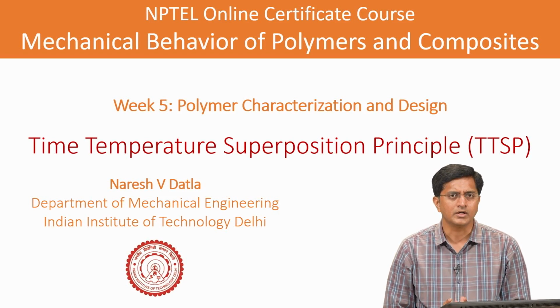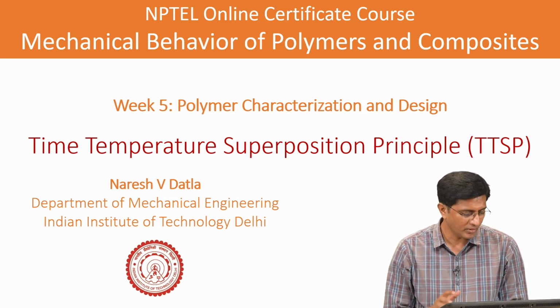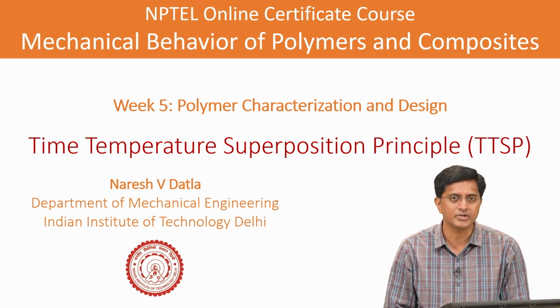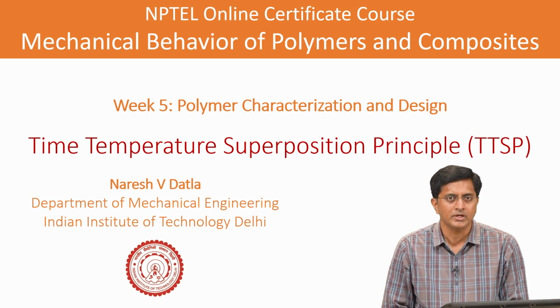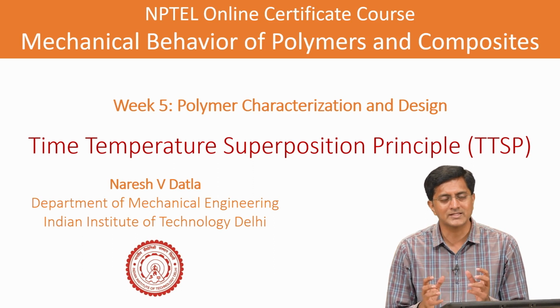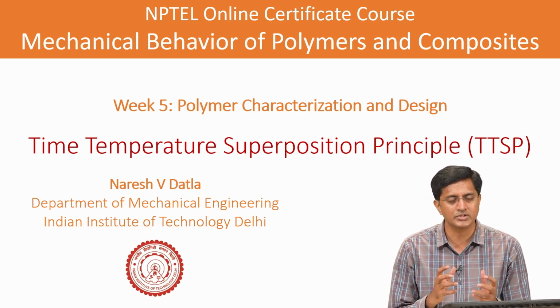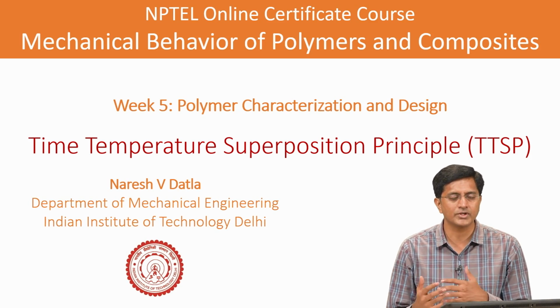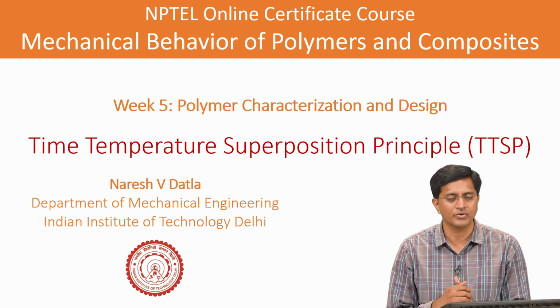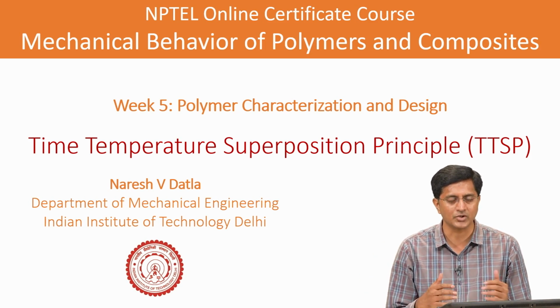Hello all. In this video, we will be looking at one more way of characterizing polymers, where we will discuss the time temperature superposition principle. Essentially, it says that both time and temperature have an equivalence between them, which means you can use one as a trade off for the other, where some experiments cannot be done, let us say for very long times or very short times.